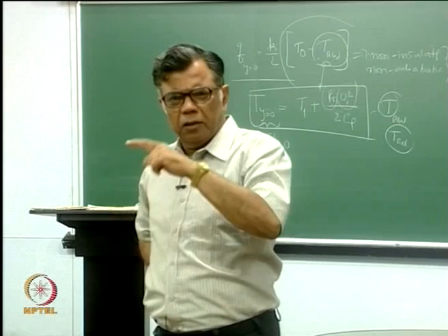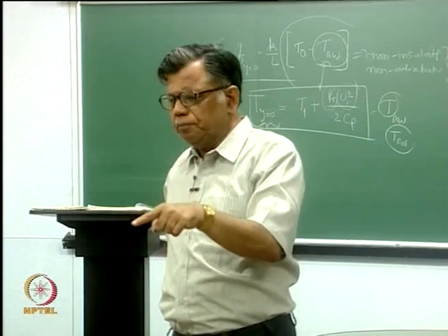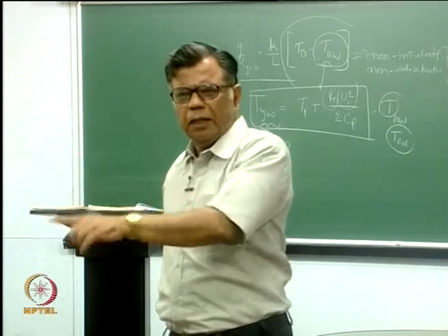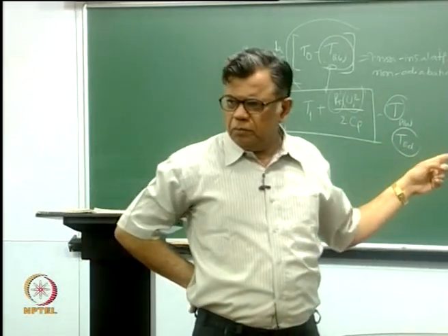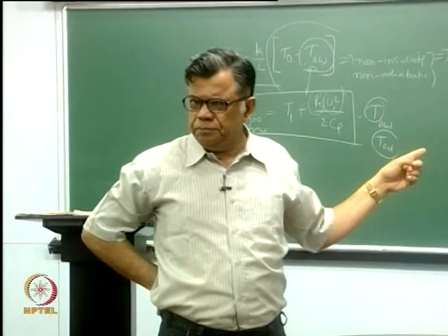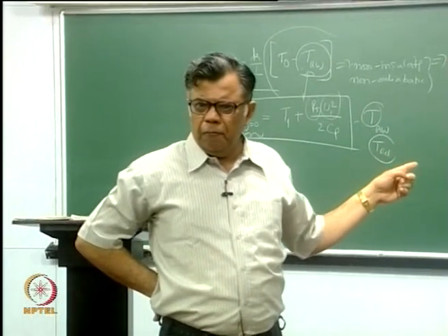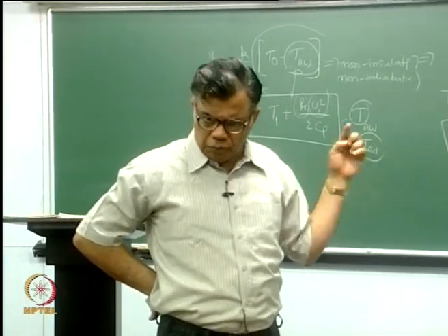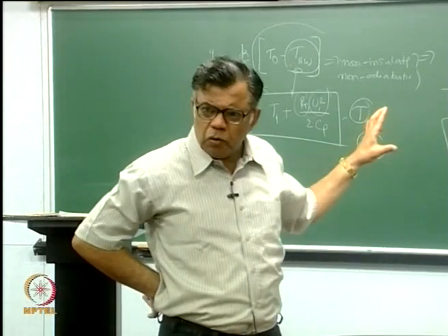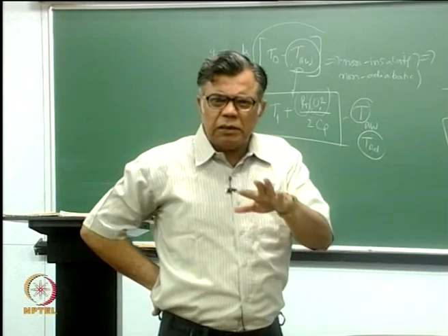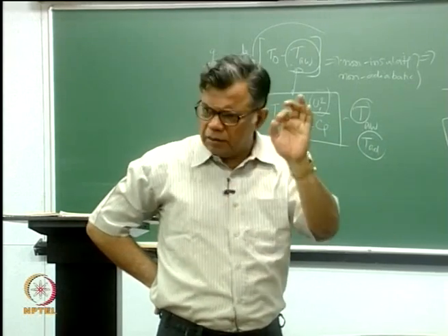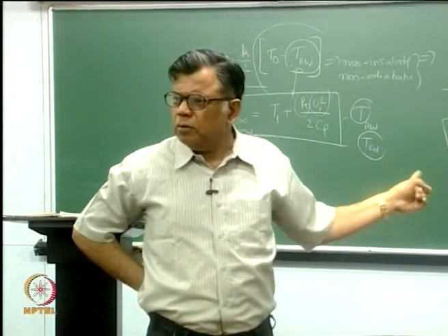A flat plate turbulent flow has its own recovery factor, which is a function of Prandtl number. A Couette flow, we did not specify the fluid here, but fluid is the Prandtl number. So for the Couette flow, the recovery factor, it does not matter whether it is adiabatic or not, that is not the point at all. Recovery factor value is equal to Prandtl.